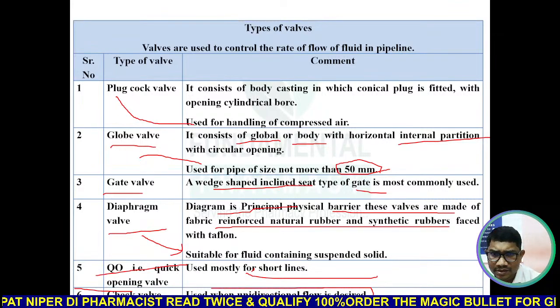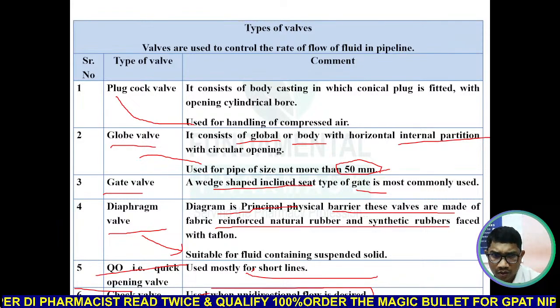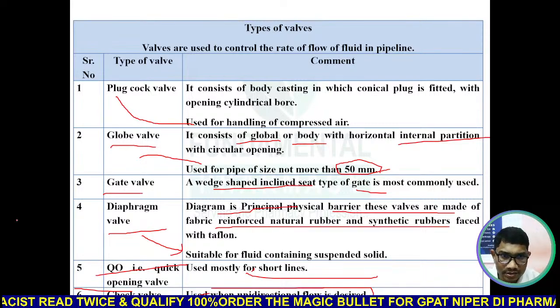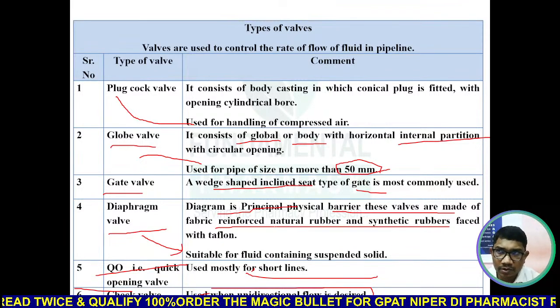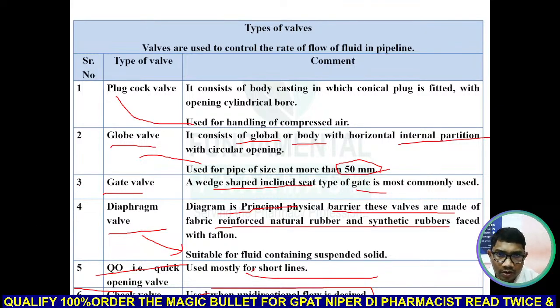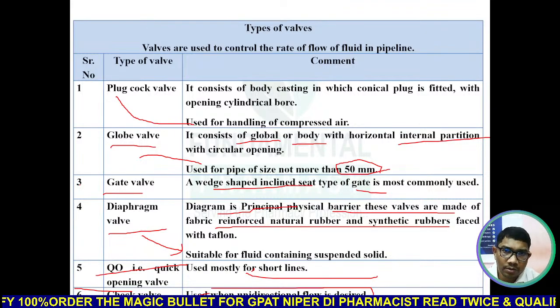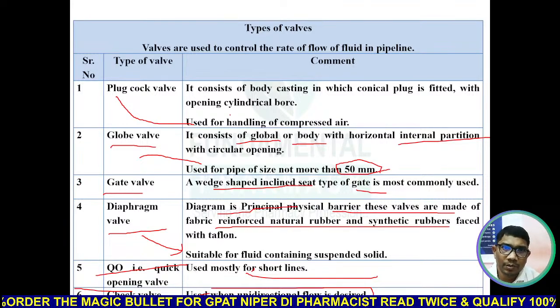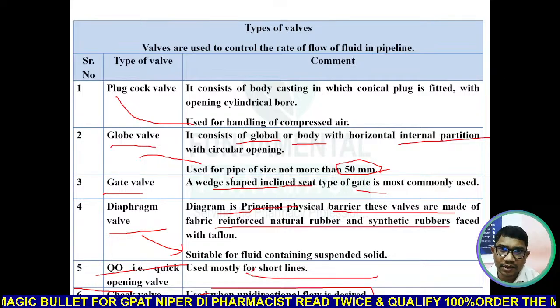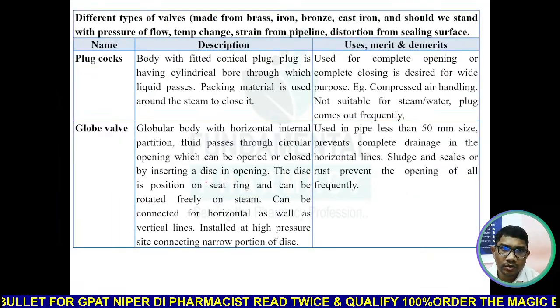Its application can come up in the exam. Check valve for unidirectional flow, quick opening valve for short lines, diaphragm valve suitable for fluid containing suspended solid, globe valve for pipe size not more than 50 millimeter, plug cock valve for handling of compressed air. Okay.